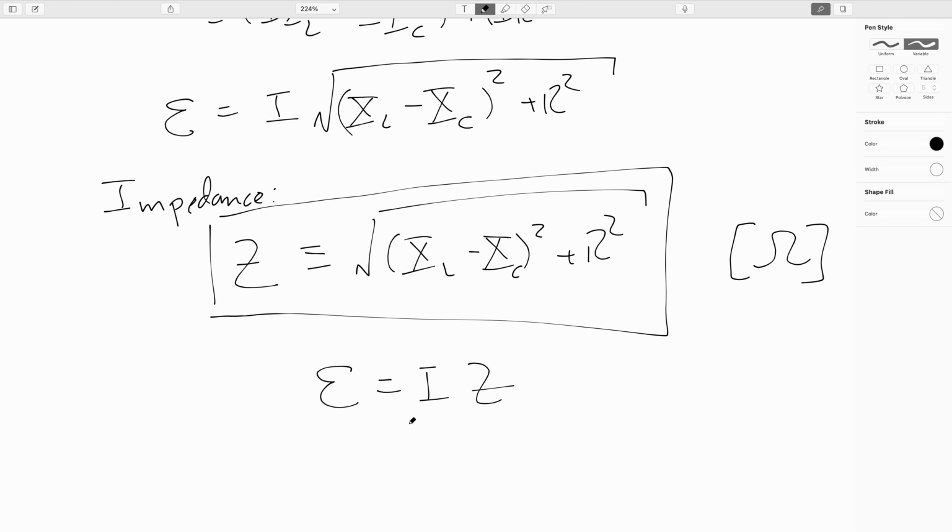So they're giant inductors, so you have lots and lots of inductive reactance. So what they are doing is they are encouraging the factory to put in giant banks of capacitors to get the capacitive reactance of the factory to match the inductive reactance of the factory. And by doing that, dropping the impedance of the factory as low as possible.